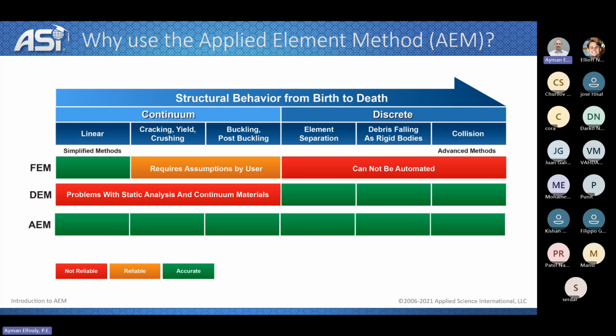One other thing here is that if you go to the discrete phase where elements start to separate from each other, this cannot be done using the regular finite element analysis where you are using frame elements or shell elements. You have to use more advanced FEM, like ANSYS or LS-DYNA, to be able to separate the elements from each other, and then you will have debris and collision.